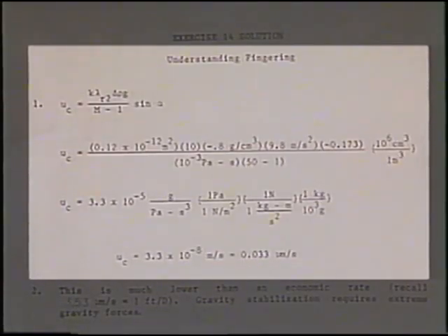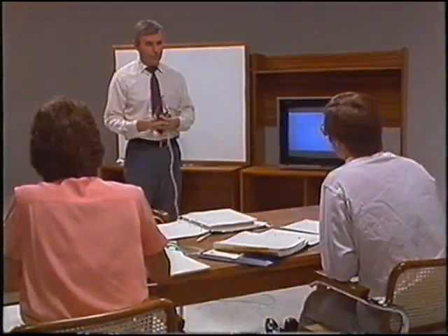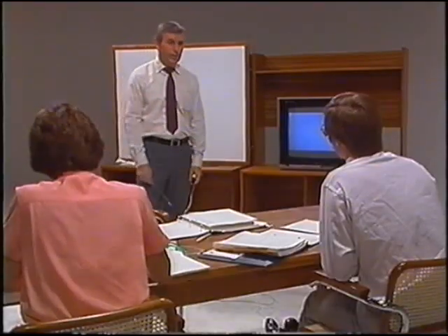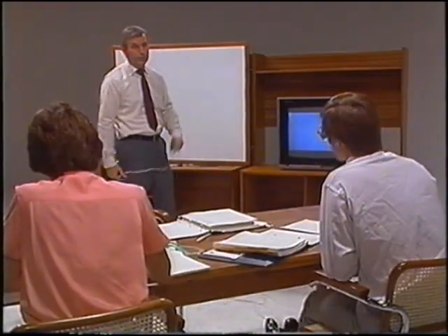Yes, John? That critical velocity meaning that you would have to have a flood rate less than that? Yes, that's right. Pretty slow. That's very slow, and so you must take the choice of whether you want a very slow efficient displacement or very fast or fairly fast inefficient displacement, and generally you take the money up front.